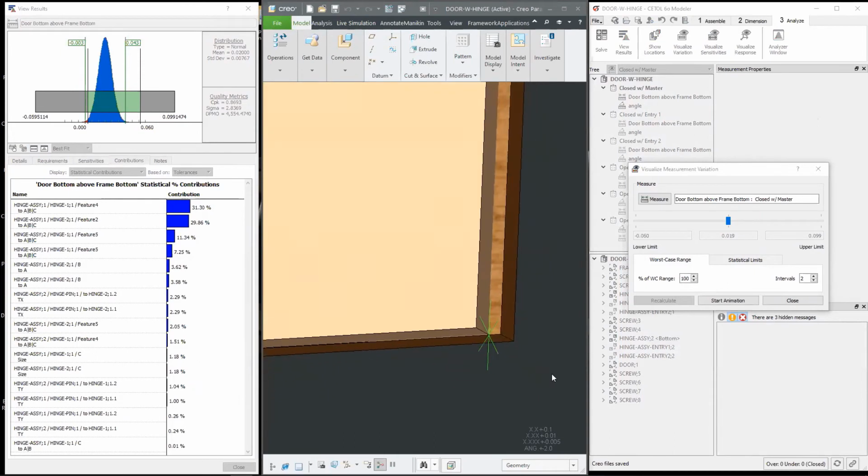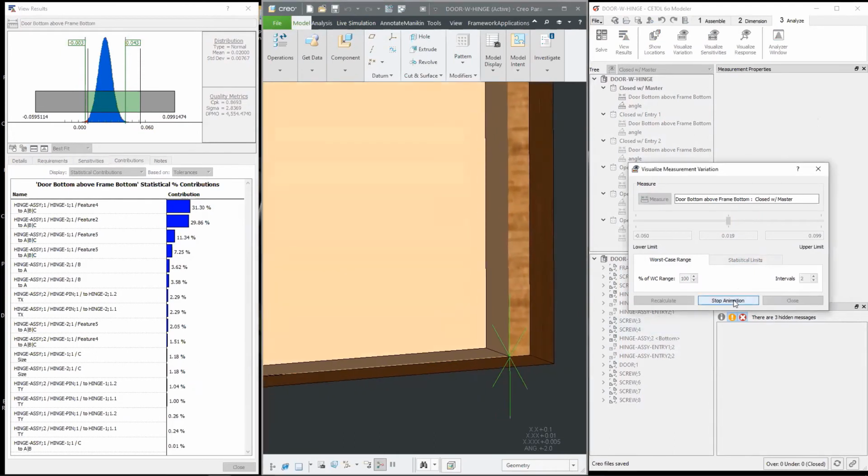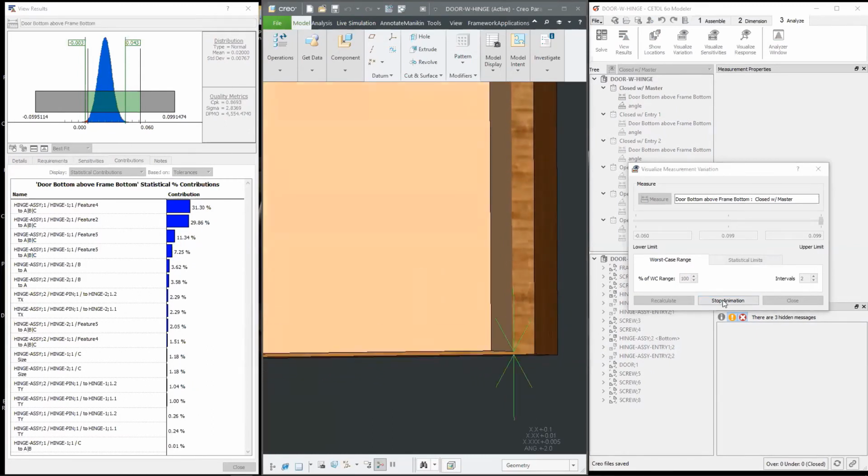So here's the door closed, and the results we're visualizing here are actually the recommended callouts of the dimensioning scheme and tolerances that were discussed last time. That's the worst case clearance, a range of worst case min and max for making sure the door has clearance.